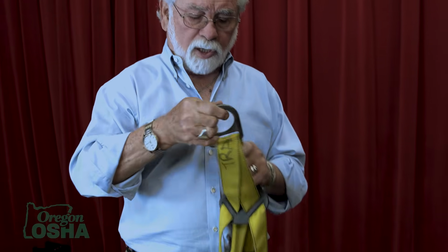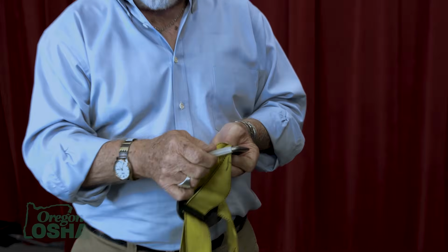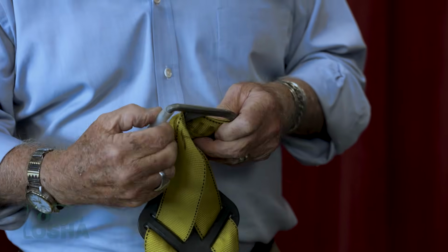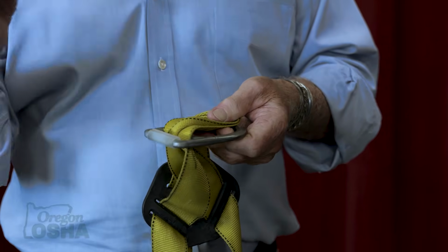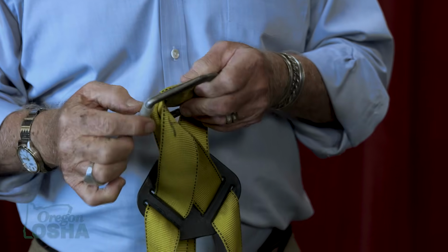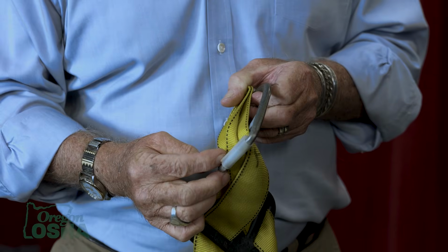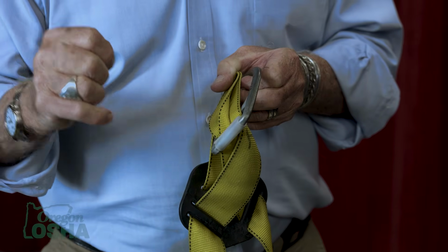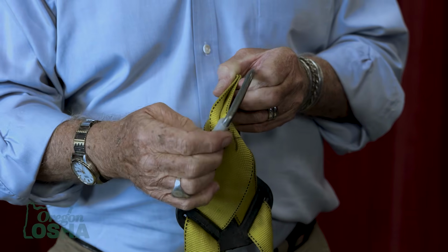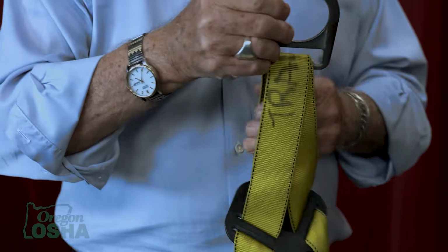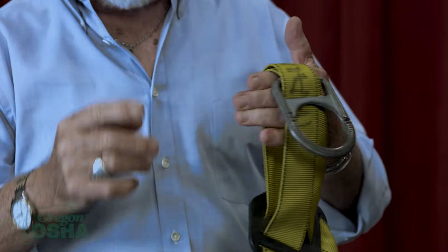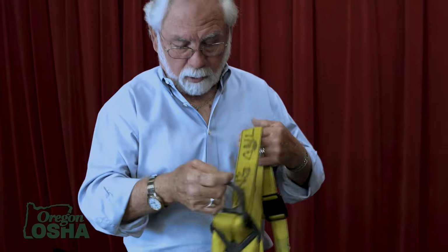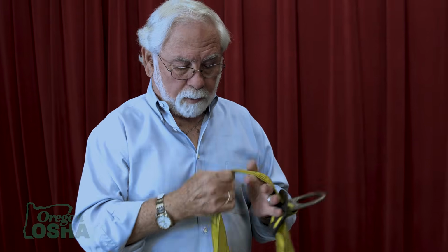You want to check inside where the D-ring goes through to make sure that there's a protector between the metal and the fabric. In this case, the manufacturer has used a plastic tube that's originally round and rotates. Here you'll notice that there is an overlap because it's had an impact, and when it impacts, that plastic collapses and it stays in that manner to warn you that the harness has been used before. And understand, all of this equipment is designed for a single time use and then it's retired. Great place to accomplish your training.